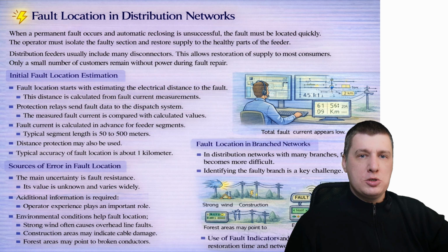In this case, the measurement fault current is lower. The calculated fault location appears further than the real one. This is a negative error. Additional errors come from current and voltage transformers, measurement devices, unknown network element impedance, and transformer position.